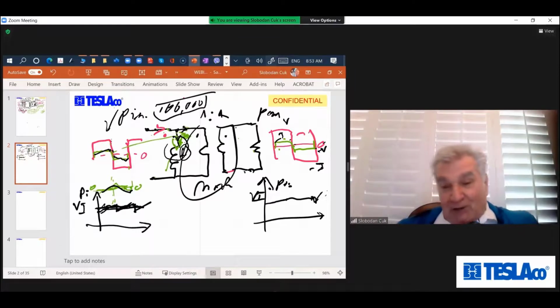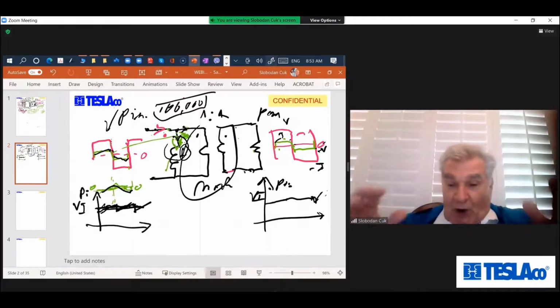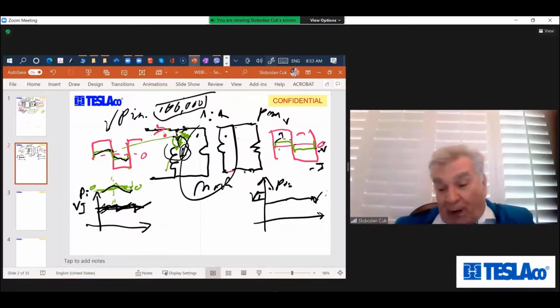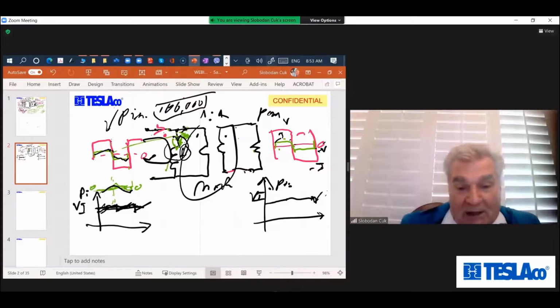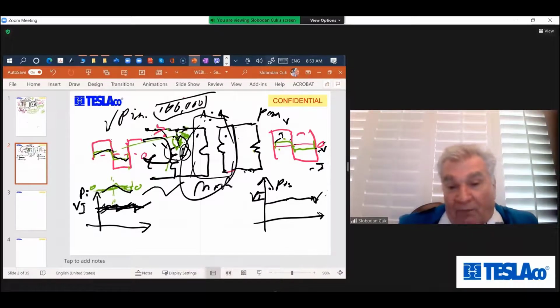This AC inductor just goes from storing energy in the inductance during on time and releasing it into your off time back into the circuit. So it's a circulating current. This magnetizing current is a circulating current, which enables the magnetic core to have a flux in it.